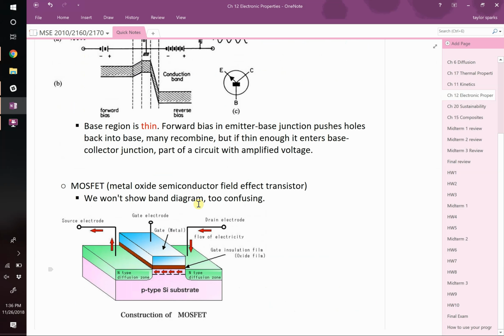Something like boron or aluminum, all over the place. So lots of holes in here. Then you take certain channels using photolithography that we talked about, you make them N-type. So you put maybe some phosphorus, I said it the other way. Now you put something like phosphorus here, something like boron here, okay? So now you've got regions that conduct electrons and regions that have excess holes, okay?